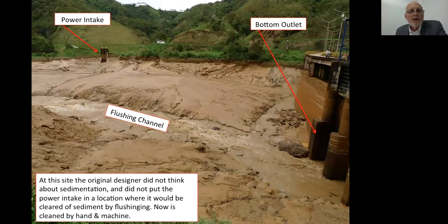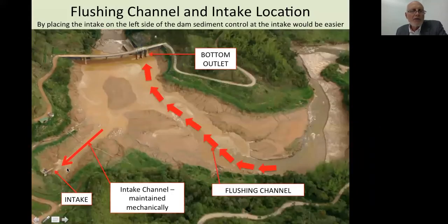In this particular reservoir, I want you to look and notice that the power intake is not adjacent to the bottom outlet. And if we look at the aerial photograph, you'll see the bottom outlet here was placed on the right-hand side of the dam. Easily could have been placed on the left hand when they did the drawings, and they did the original design. And the intake could have been extended so that when they opened the outlet for flushing, the channel would have cleaned the intake.